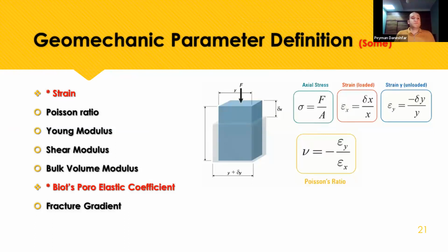Here, we just talked about the stresses. Now we know what vertical, horizontal, minimum and effective stresses are. A fracture will propagate perpendicular to the minimum stress, and all these are parameters that you should know about the stresses.